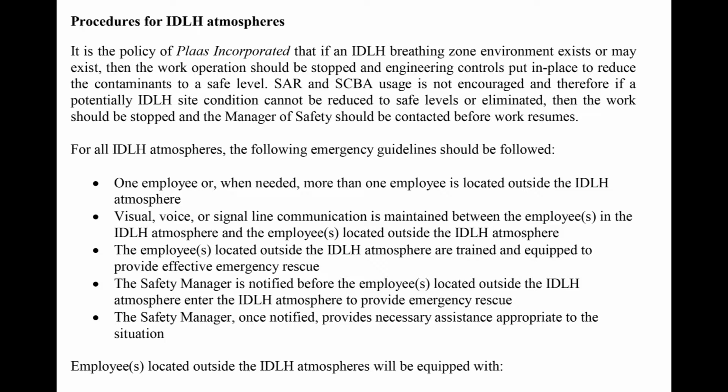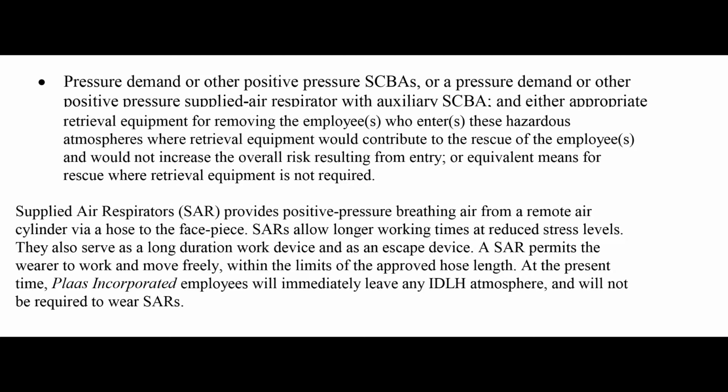Employees located outside the IDLH atmosphere will be equipped with pressure demand or other positive pressure SCBAs, or a pressure demand or other positive pressure supplied air respirator with auxiliary SCBA, and either appropriate retrieval equipment for removing employees who enter these hazardous atmospheres, where retrieval equipment would contribute to the rescue of the employees and would not increase the overall risk resulting from entry, or equivalent means for rescue where retrieval equipment is not required.